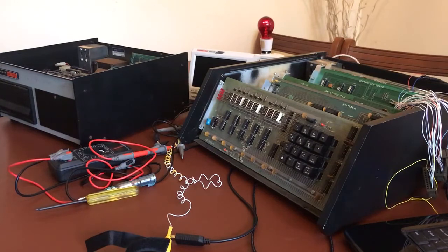So 99% certain there's a few chips in there. I did want to do a bit more today, maybe on camera, to look at which bits it was exactly, because it may be more than 2 of the chips that are faulty. There's quite a few addresses, I think about 8 that have got faults. Some seem to have stuck 1 bit and some seem to be able to go to 1. So that probably indicates 4 chips are faulty in that row.